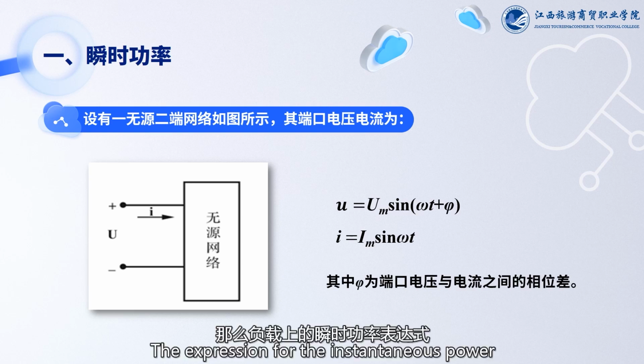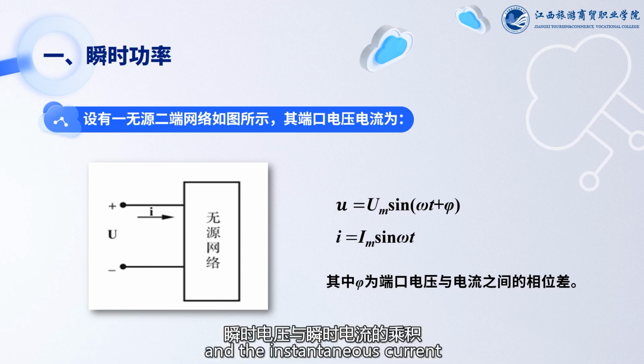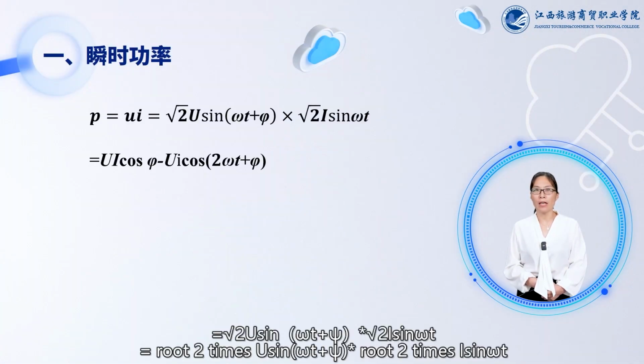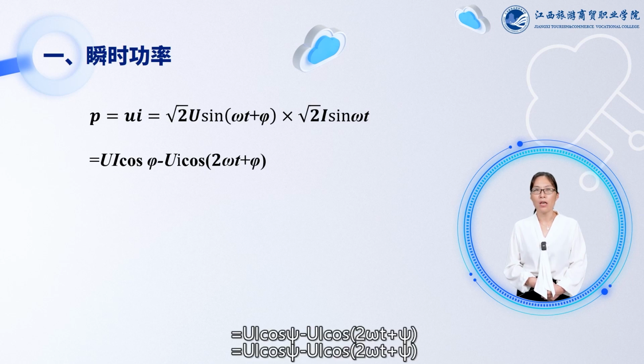The expression for the instantaneous power on the load should be equal to the product of the instantaneous voltage and the instantaneous current, namely p equals ui equals √2 U sin(ωt plus φ) times √2 I sin ωt, equals UI cos φ minus UI cos(2ωt plus φ).